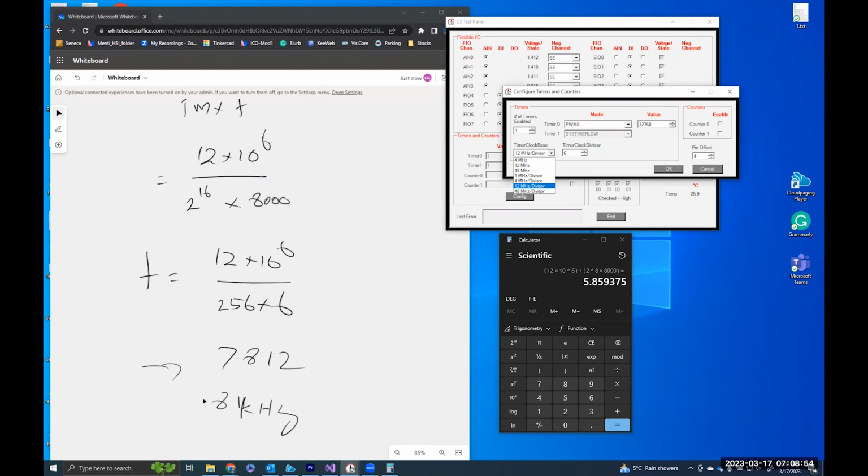If you want to find 12 kilohertz, what would you do? You set everything accordingly. Maybe you can put it to 16 and then 48 here, and then play around with the number. You already know the frequency that you need is 12 kilohertz. So apply that number in this frequency and find the divisor to get the intended signal. So now we know why we have the divisor and why we don't have the divisor.